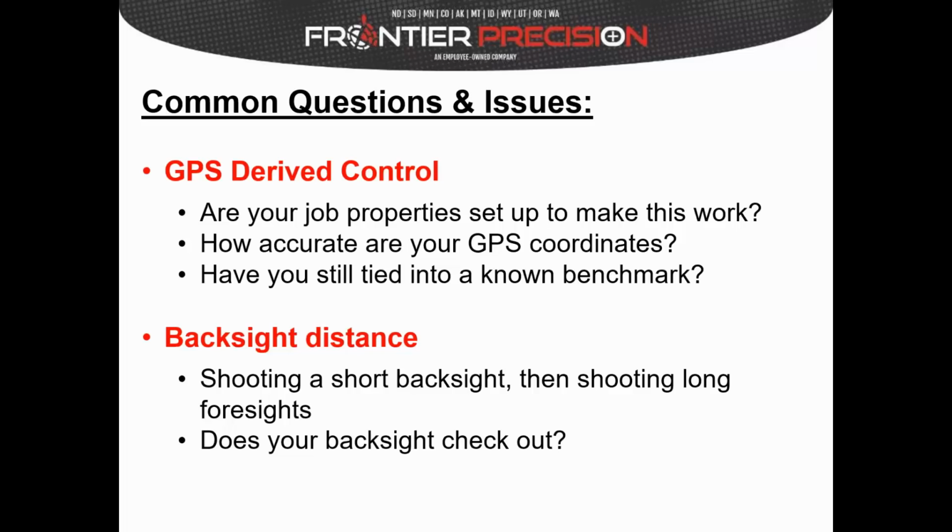So when you do the station setup, you will see how well that backsight checked out. You should be taking a look at that and making sure that it's right and fixing any errors before you store anything. This happens a lot, so just be wary of that. I believe in your survey style there's a view before storage checkbox. I always like to recommend having that on so I can see how everything looks before I hit the store button and make sure that it's right.